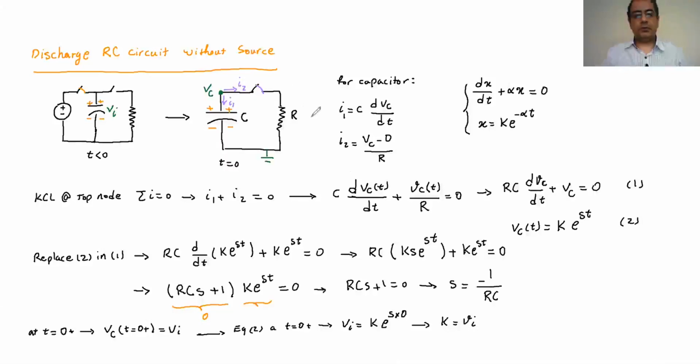So one more time, very quickly go over that. We have the capacitor. We fully charge that capacitor. Then after we fully charge that capacitor, we remove the battery and we connect the capacitor to resistance. As soon as we connect the capacitor to resistance, the capacitor starts to lose energy, and its voltage starts to drop.